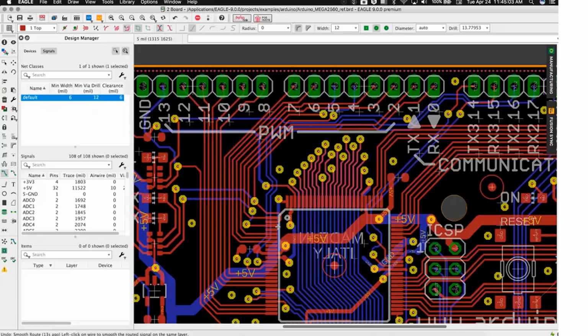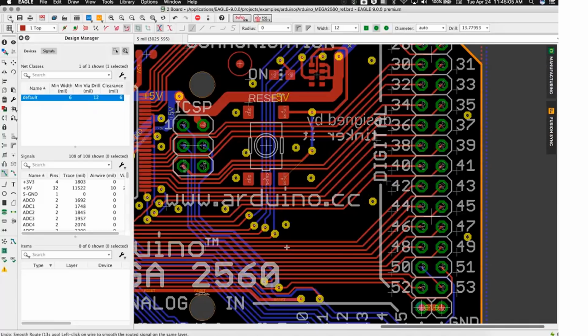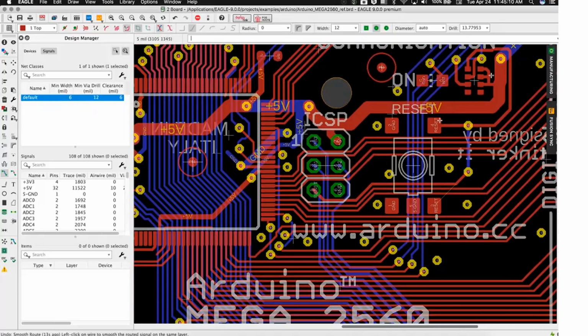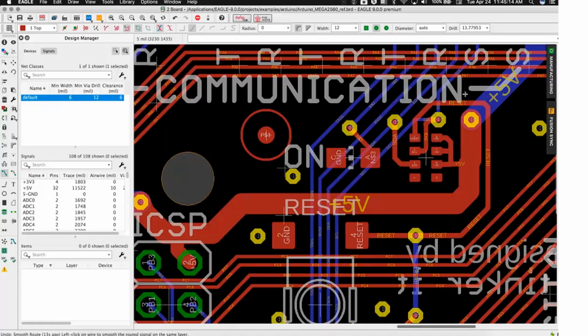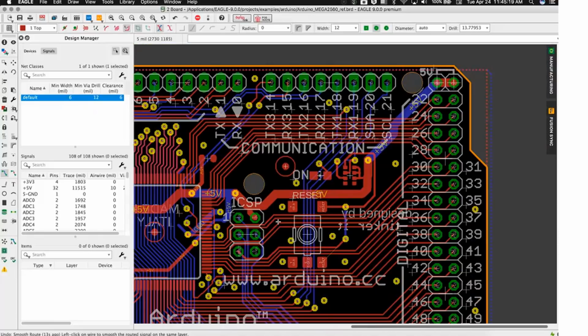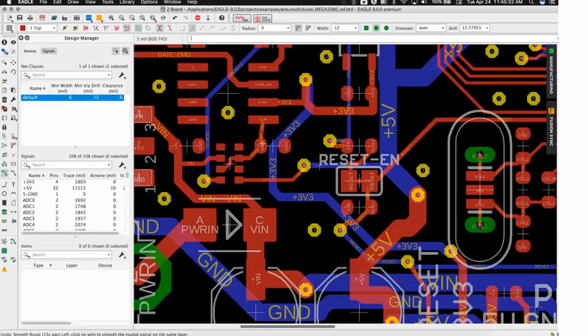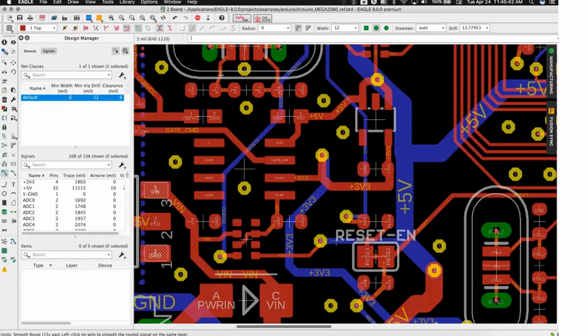Lots of really cool, really powerful kind of cleanup glossing passes that we can run on top of connections on the board. And again, this is just intended to make it much, much easier for those of you who are going through the process of kind of faithfully tidying up your design and saying, hey, I really want to make this look amazing. We can go through and do some cleanup on things, reduce some of the additional segments, reduce some of the additional jogs in these connections over here, and just make the design look better without you having to do a whole bunch of work. So you'll see it even has the ability to clean up those non-ortho connections. And again, it's going to take a lot of length out of the routes in your design.